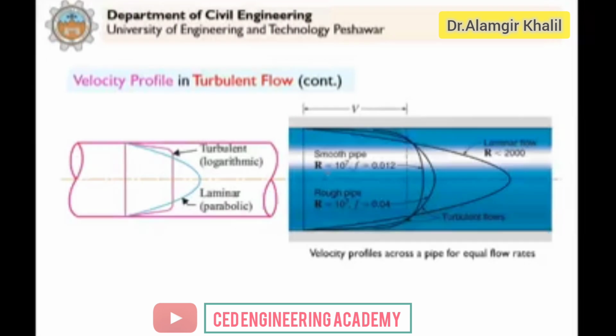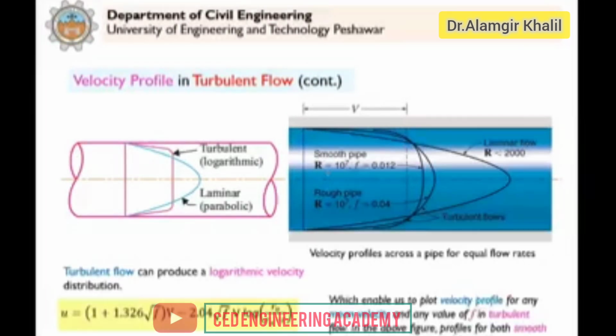Then we discussed the velocity profile in turbulent flow. In that case we studied that in turbulent flow, the velocity profile can be represented by a logarithmic velocity profile, because you can see here the log. And we already saw a video last time in the class that experiments also support that it follows a logarithmic velocity profile. Clear? So this equation has a proof, but for the sake of saving time, I skip the derivation.